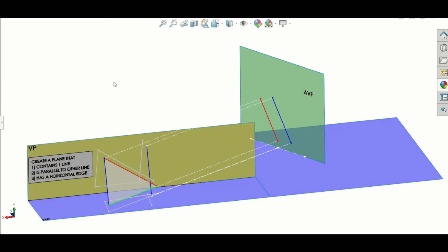So to take it on to the next stage now, from here we are looking at our two lines appearing parallel, just like we got there on paper. The 3 ways that the question could be posed: we could be asked for the shortest distance or perpendicular distance, which is the same thing. We could be asked for the shortest horizontal distance between the lines, or we could be asked for the shortest angular distance, so the shortest distance that is at a given angle. Either way, it all comes from here. This is the key point right here.